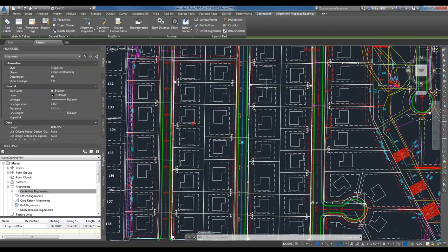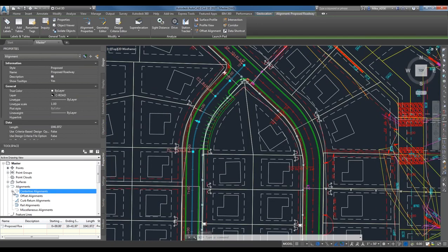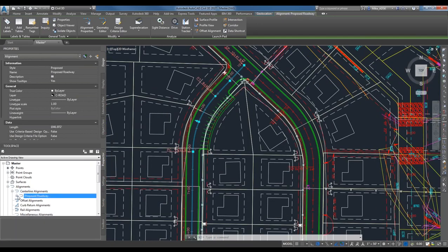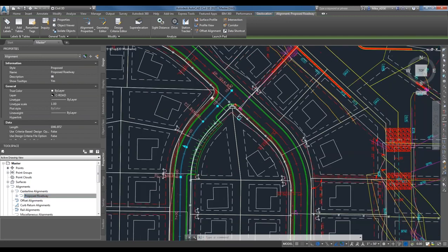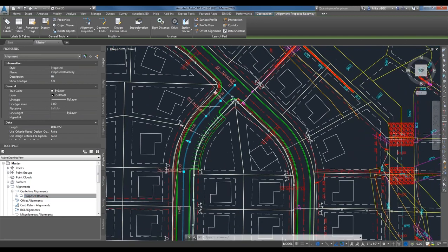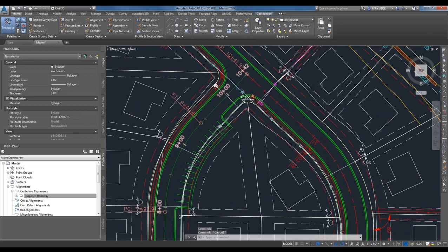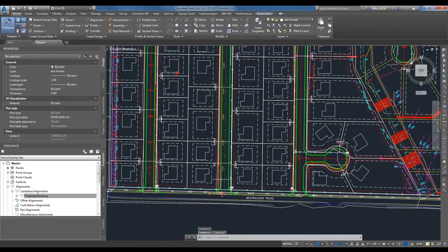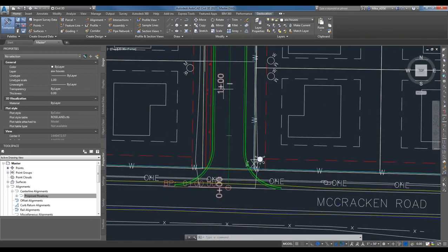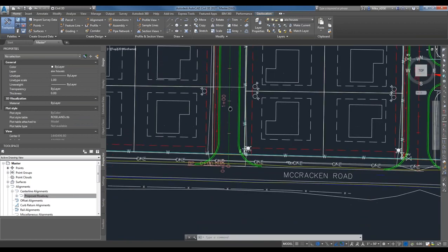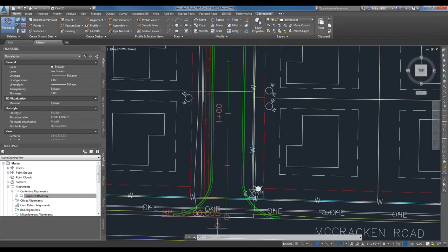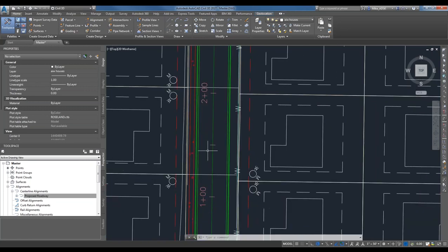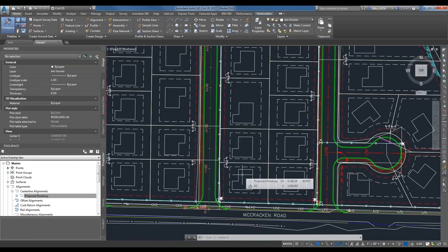What's the difference? Now, if I were to go to the tool space down here, you could actually see that my proposed roadway is here. You also see that it labeled. So there's stations over here. Your station 0+00, 1+00. Best way to think about that, it's in hundreds. So from station 0 to station 1, that's 100 feet. From station 1 to station 2, it's 100 feet.